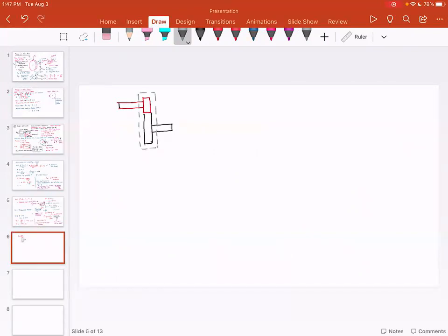And there are two shafts. So this is shaft 1. This is shaft 2. Ideally, you want to design both the shafts. And why do we need to design both the shafts? Because if you think about it, the torque here and torque here, so if this is TP, this is TG, TP and TG are different.